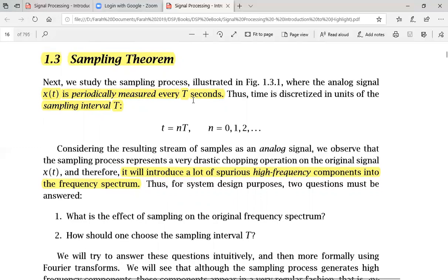When you convert continuous time t into discrete time, t would be replaced by nT, where n is an integer from 0 onwards and T is your sampling interval. For example, when n is 0, you are collecting your first sample.